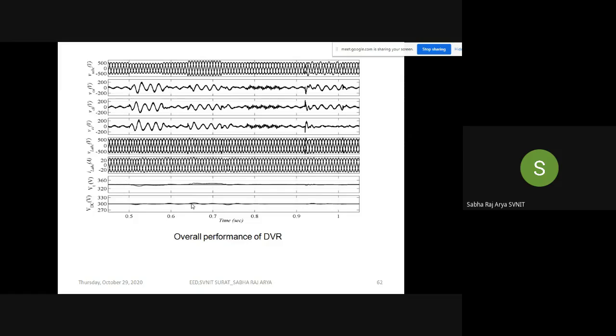Okay. For the second case, how can we check whether our PI is working or not working? See here, at around 0.65 we have created a set point change, and our DC was also going to change. After the change, it has got some deviation, maybe 10 or 5 volts, and again returned back to the reference level with some oscillations. Here it means the value of Ki is somewhat higher.